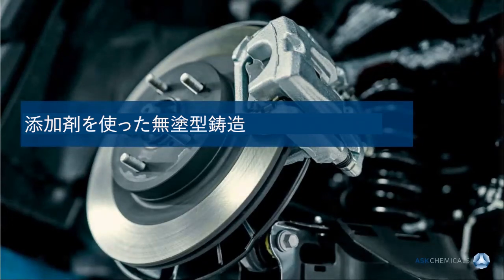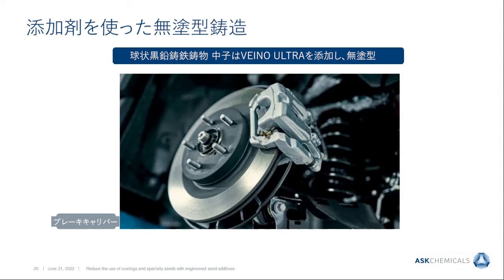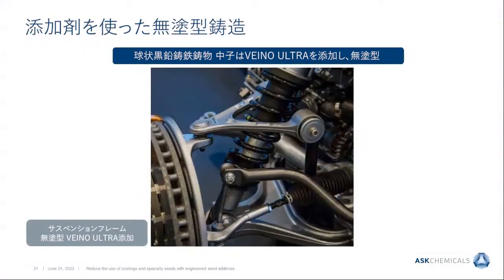What about coating-free casting when we use additives? Here we have an example. You see on the picture the brake caliper which is cast out of ductile iron. Before, it was coated with our coating, and we substituted the coating process with our additive Veno Ultra. And the casting quality and surface was good enough that they can sell these castings.